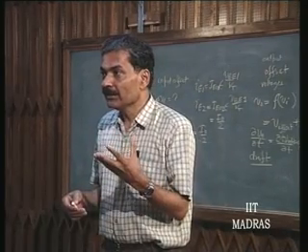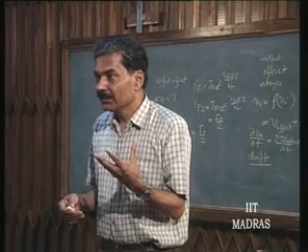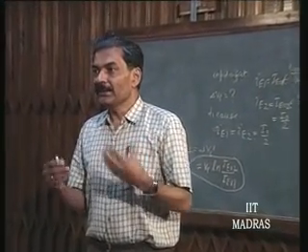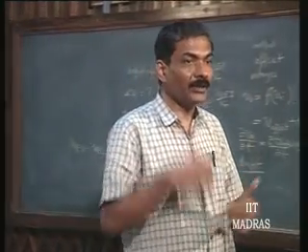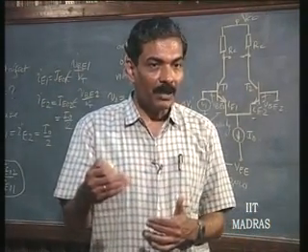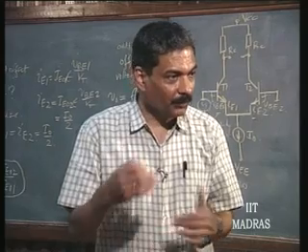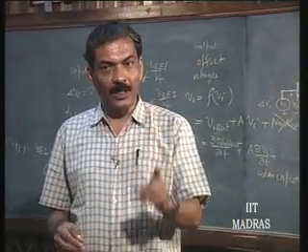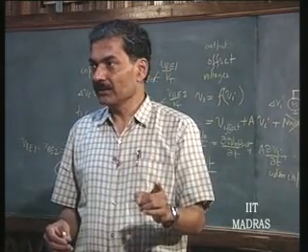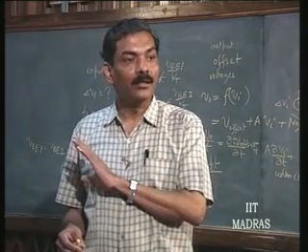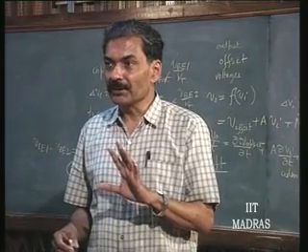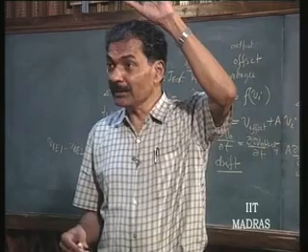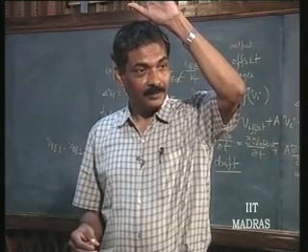That is uncertainty in VGS. For obtaining the same current, the uncertainty in VGS is going to be one order of magnitude higher than in the case of a bipolar transistor, that is for the MOSFETs. So please remember, if input offset is the choice for the input stage, then MOSFETs are out of the question as input stage. You would rather prefer bipolar stage, but MOSFET has given you the highest input impedance that can be given.